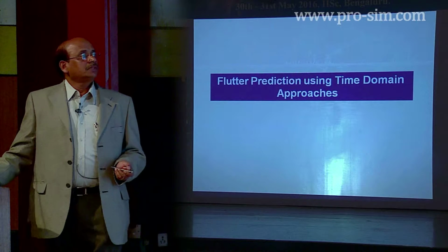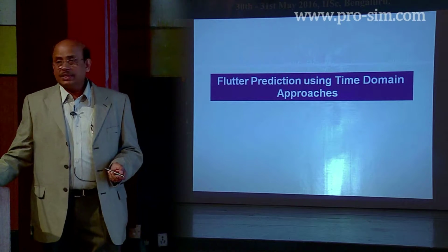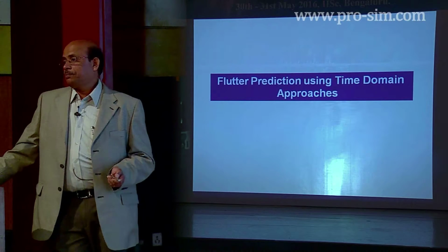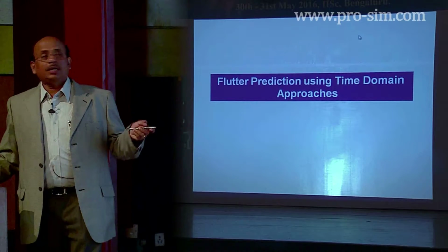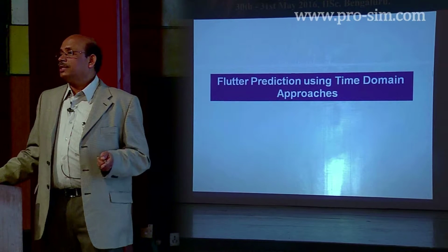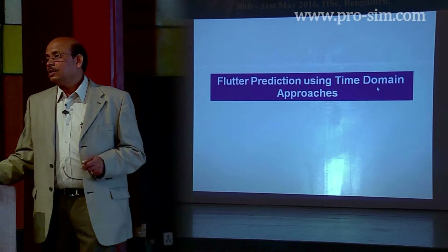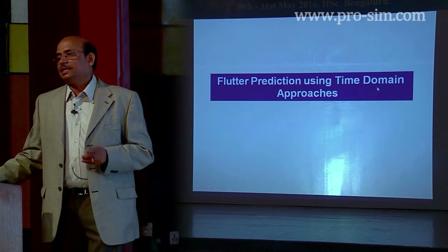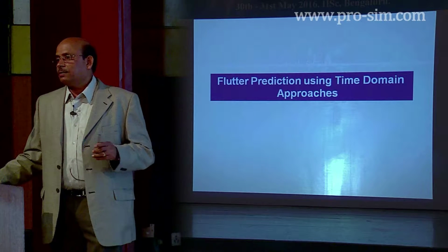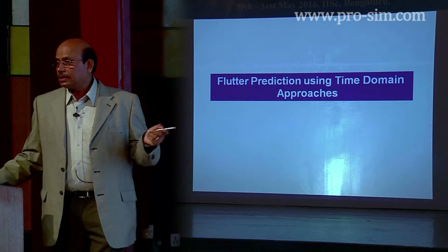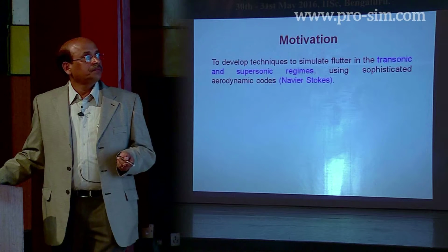Then we have the next class of methods, what are known as flutter prediction using time domain approaches. This is what I was telling. It is one of the most high fidelity methods that are available, which makes use of all the methods like the finite element method, finite difference method, all the methods available to us. Such methods can be used in this approach.